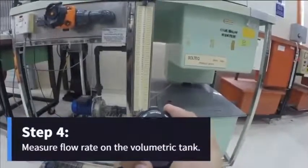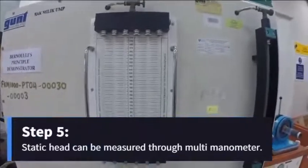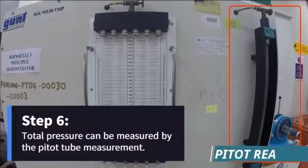Step 4. Measure the flow rate on the volumetric tank. Measure the static head through the multimanometer. And lastly, the total pressure can be measured by the pitot tube measurement.